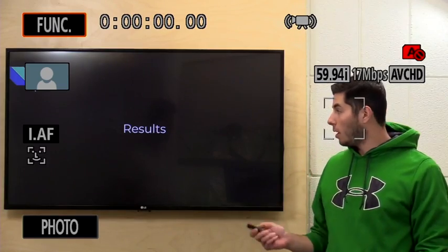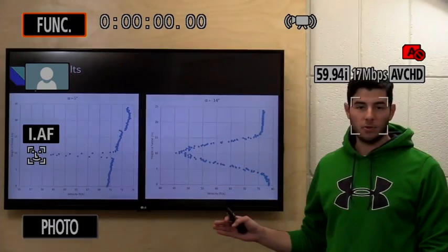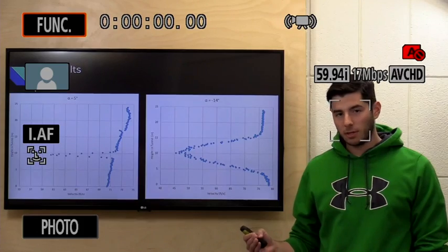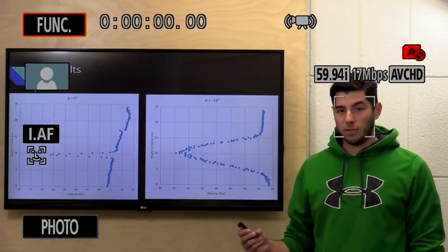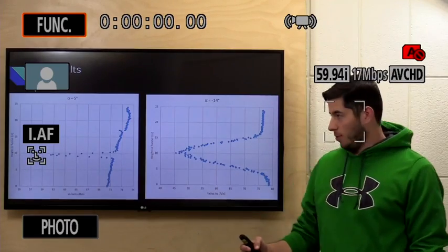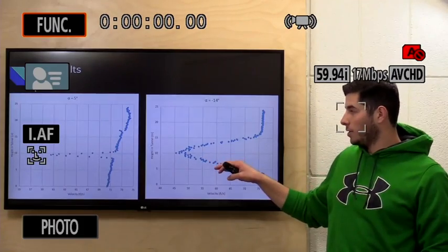I'm going to be discussing the results of the experiment that we found from the 2D wind tunnel testing. The first thing we were tasked with finding was the velocity distribution behind the airfoil as a function of the height in the wind tunnel. As Connor mentioned, this is why we're using the hot wire anemometer to measure the velocity of the air after it passed over the airfoil. We used angles of attack of 5 degrees and 14 degrees.